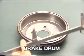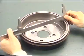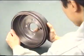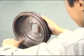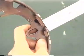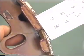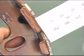Inspect the rear brake parts. First, measure the inside diameter of the brake drum. The brake drum should be replaced if not within specifications. Then make sure there is no abnormal wear or damage. Measure the brake shoe lining thickness. Minimum thickness is 1 millimeter. The brake shoe must be replaced if not within specification or if it is close to minimum tolerance.